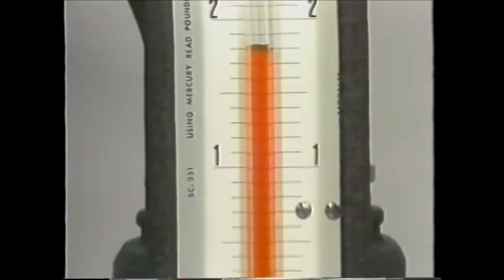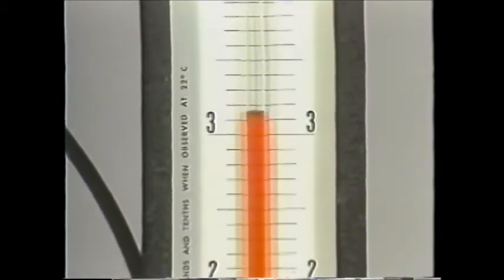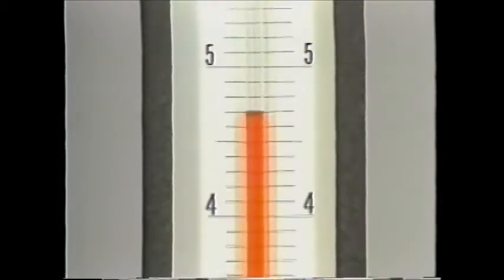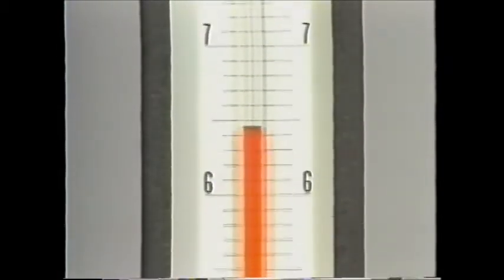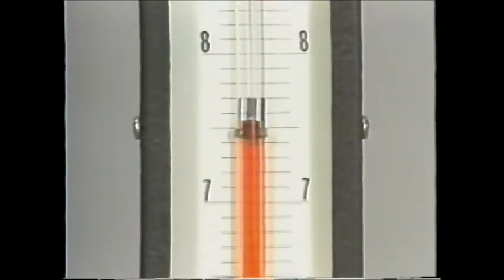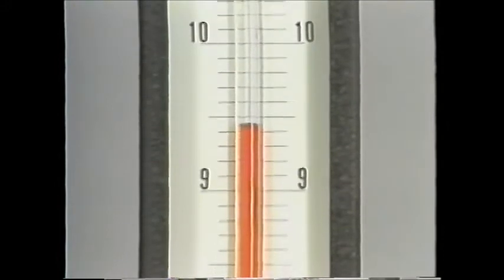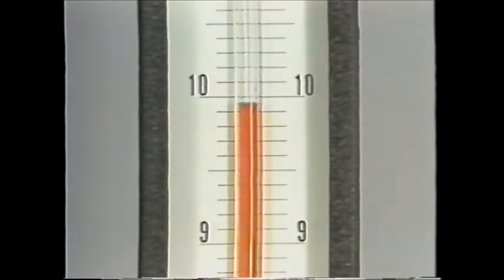As the pressure on the liquid changes, it causes the liquid level to change until the hydrostatic head of the liquid in the manometer equals the pressure being applied. The pressure value is read in inches of liquid. A change in pressure of 1 psi is equal to a change of 27.7 inches of water. Manometers like this one are sometimes found in industrial applications.